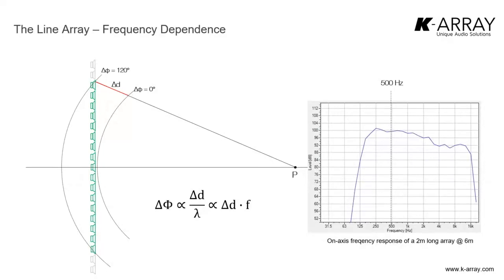If a long line array is too dark, you can just use an equalizer to reduce the mid-lows a little bit. That's what I usually do, especially when I have like a 6 or 8 meter long line of cabinets, right? So absolutely no problem.